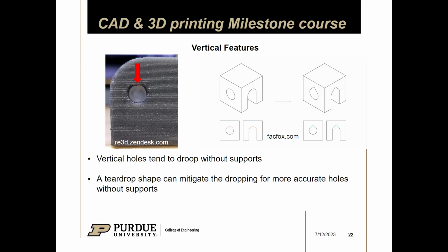It's something that I didn't really think of when I first started making stuff, but technically, if you have a vertical circle, the top of the circle is going to be a really aggressive angle, and it's going to be an overhang. So you see on the gray part on the top left, the top of the circle is drooping, and that's because it's technically an overhang.